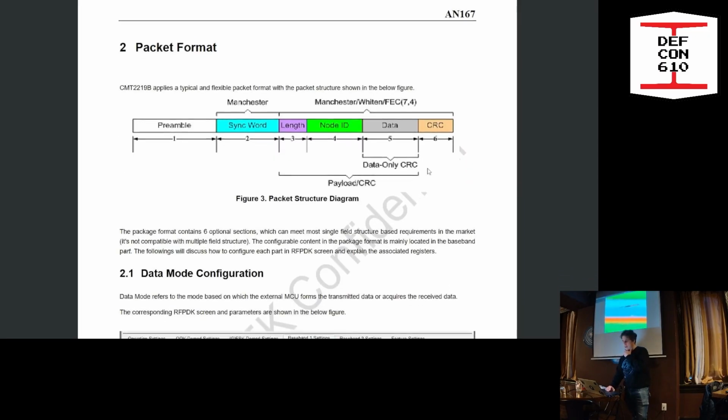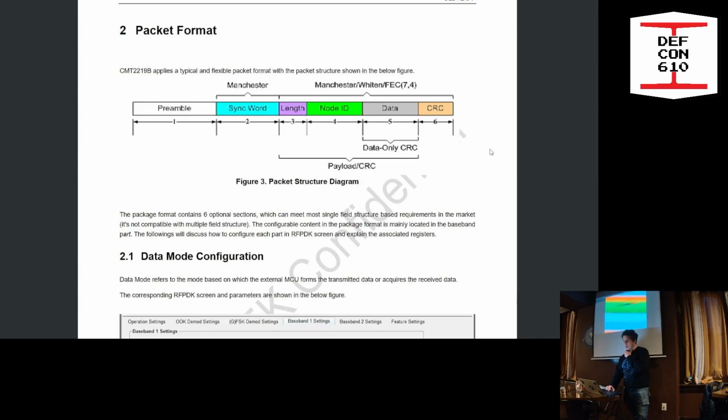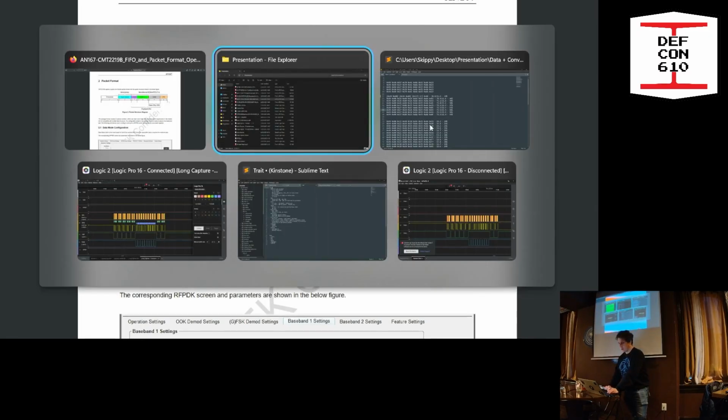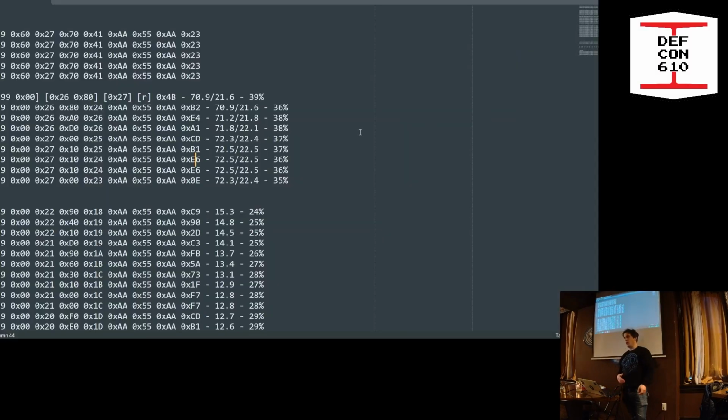Here, so basically you can encode the data, and it has a CRC in it. So you know basically that the CRC is probably calculated, and so you don't have to worry about that. You can also do logical checks. If the humidity is higher than 100%, you know it's invalid, and you can basically do safe ranges.